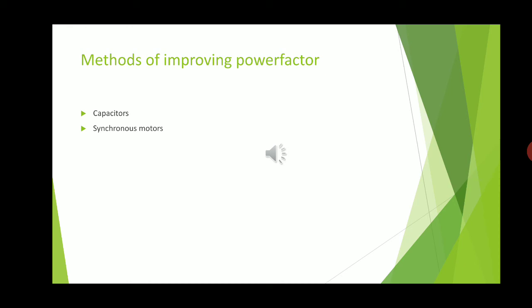If you recall the diagram for the resistor load, what happens to the current phasor? It is parallel to the voltage phasor. So we can conclude here, if the phasor angle difference is lesser, that means the current phasor is more towards the voltage phasor. What will happen? The overall power factor of the system will increase. It will go towards one, because it will have lesser phasor angle.